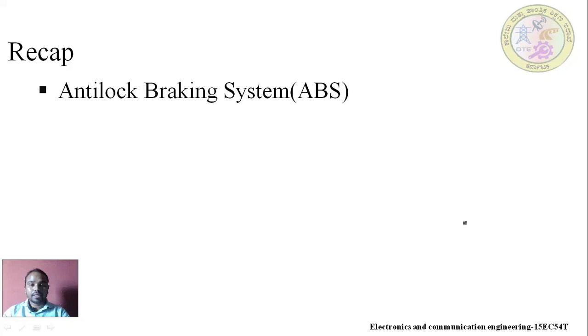Assume that the ABS system is implemented in the vehicle. When a driver presses the brake pedal and the wheel is about to stop, that information goes to the wheel sensor within a fraction of a second, and the captured information is given to the ECU.